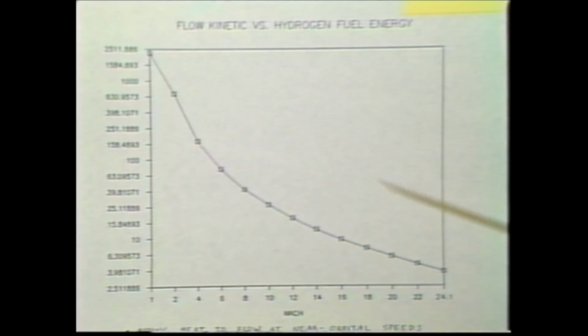Dr. Lewis talked about that the eta KE, or the inlet efficiency, was always about 0.97, and the nozzle efficiency will be similar. It'll always be about the same number, not varying by much more than maybe 1%. The reason for that is you're at such high velocities, you don't change the velocity much through the flow path, and he illustrated that. Velocities do not change much. You don't hit the flow very hard to increase its pressure and do all the things thermodynamically you want to do through the engine and flow path. And that's why it makes the high-speed performance also very sensitive to how good an efficiency you have.